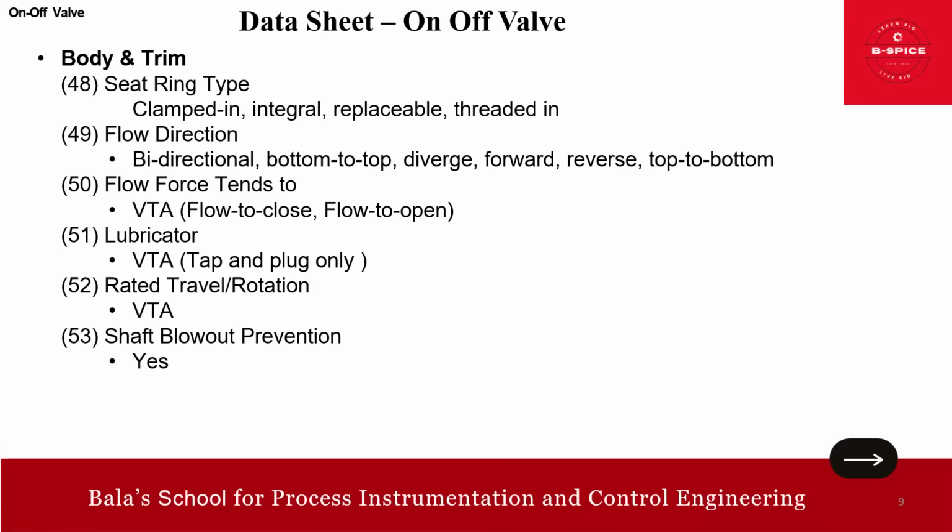So what is shaft blowout? In certain types of check valves and butterfly valves, the drive shaft connects the internal valve disc to an external component, such as a pneumatic cylinder or counterweight. If the drive shaft becomes disconnected from the disc due to a failure, it can lead to a catastrophic event like a shaft blowout.